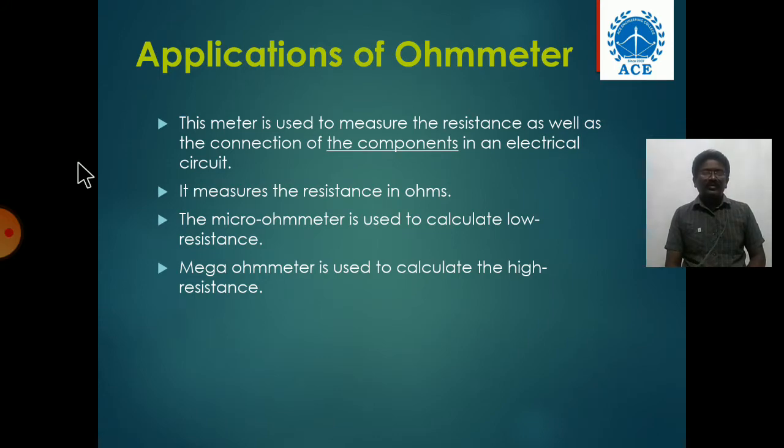So this is the calibration position of series type of ohm meter. By using these movements, now we can measure our required multiplier resistances R1 and R2. By using this procedure, you can calculate value of R1, R2, and you can calculate off scale deflection movements also. So now you have to calculate middle value of the unknown resistances.